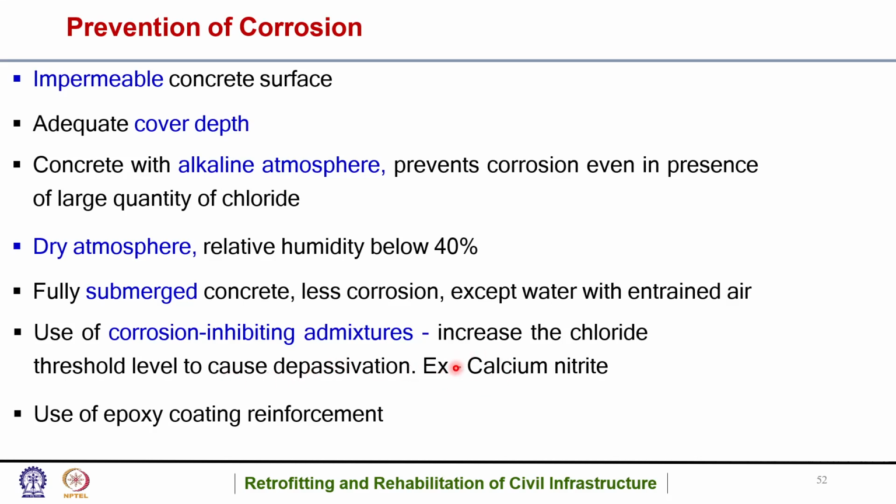Okay, so for example we can take calcium nitrate. It will increase the chloride threshold level to cause depassivation. And also we can go for epoxy coating of reinforcement. That will also provide an extra layer of protection.